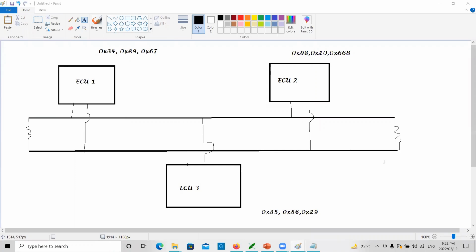It's all about how many messages there are in each ECU. If you have only one message each, totally you will have only 80 messages. One message in one ECU means that even with 80 nodes you only have 80 messages. It depends on your bus load, the number of messages transmitted by the ECU, and then your OEM and your product, everything. That area is still gray. There is no benchmark to say only this many ECUs can be in a network. That's all.